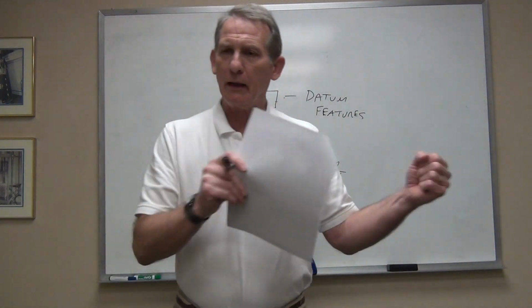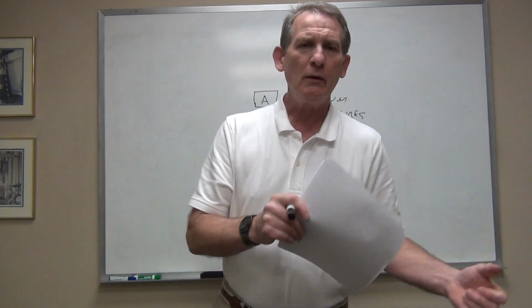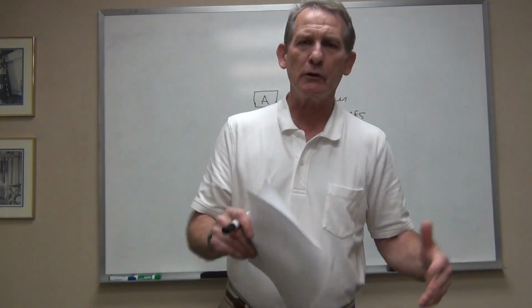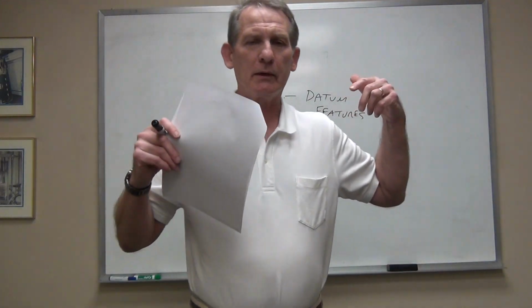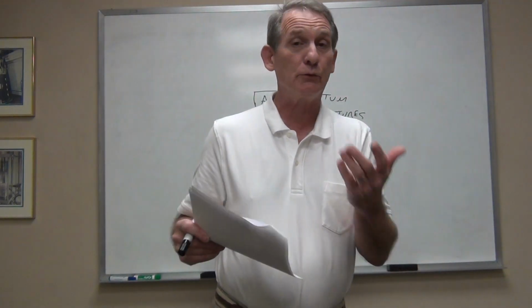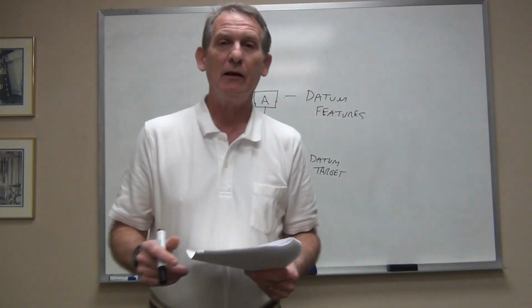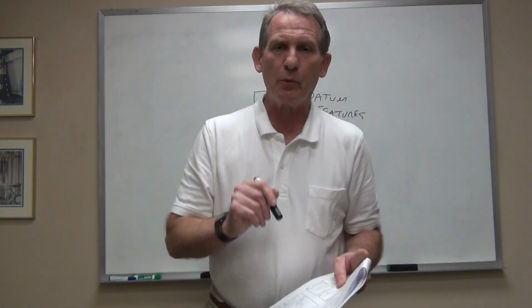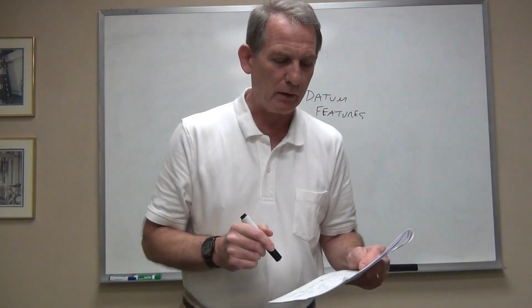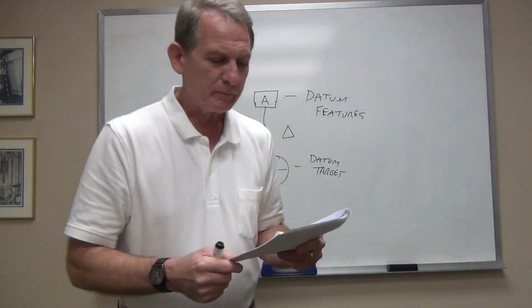Once you take that component off that fixture though, those points aren't there anymore. You couldn't look at that part and say, oh yes, I measured from here, here, and here, because those features cease to exist. They never really did exist. We were just picking specific points on a part to measure from.